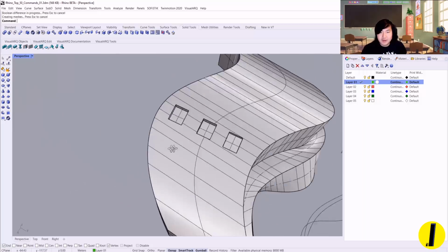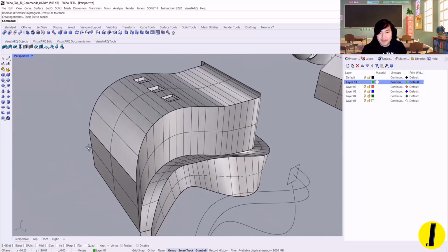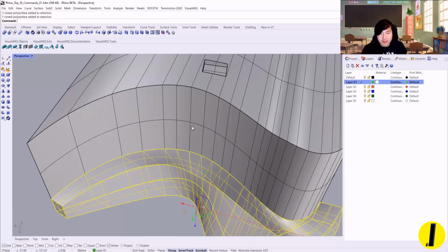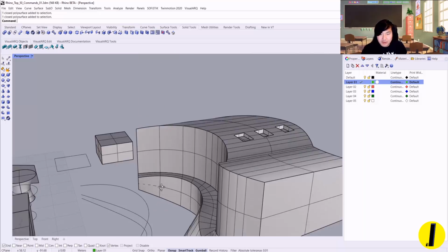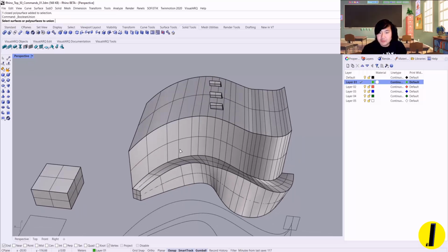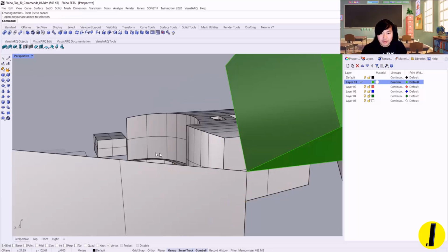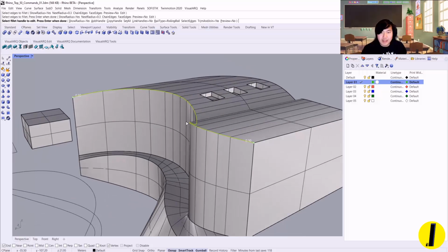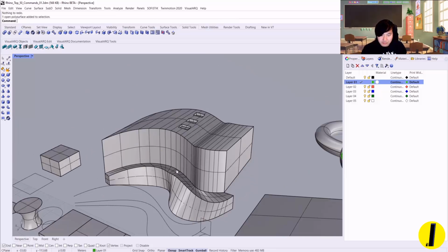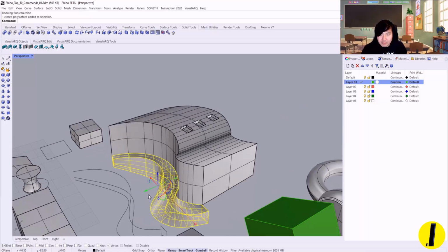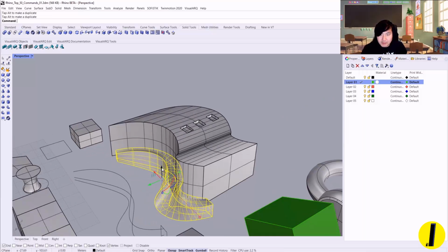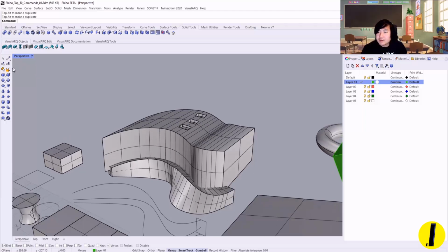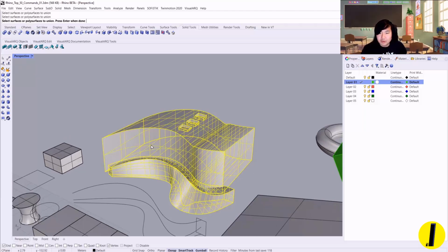So you have this Boolean operation, and in this area we can actually union them. So I'm going to use Boolean Union 1 and 2. So they are now a unioned solid object, and perhaps we can use this fillet edge. When I click here, it doesn't let me fillet because I just joined them as edges. So let me cancel, undo, Control Z. I'm going to push this a little bit further, and put it up a bit so I can join them. So let's use Boolean Union 1 to union it.